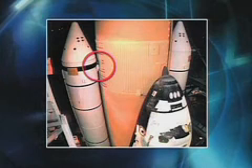This is the forward attach point between the SRBs and the external tank. That's actually the thrust post on the SRBs that transfers all of the forward thrust from the SRBs into the external tank and subsequently into the orbiter itself. And the bolt catcher is a high-tech term for a catcher's mitt, if you will. It actually describes its function.